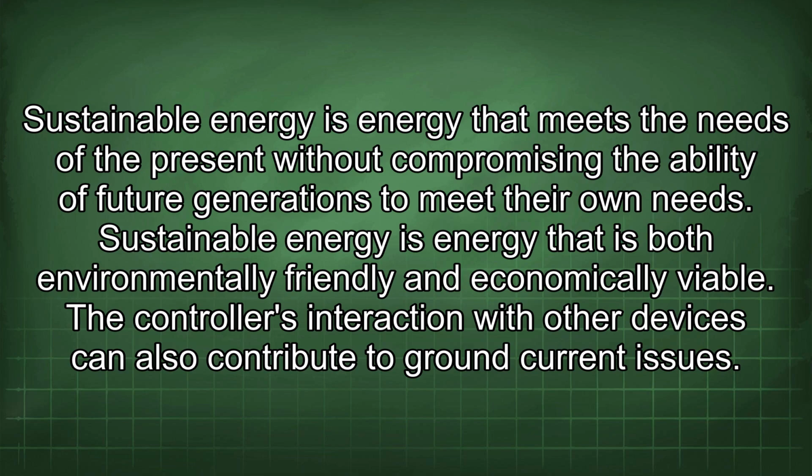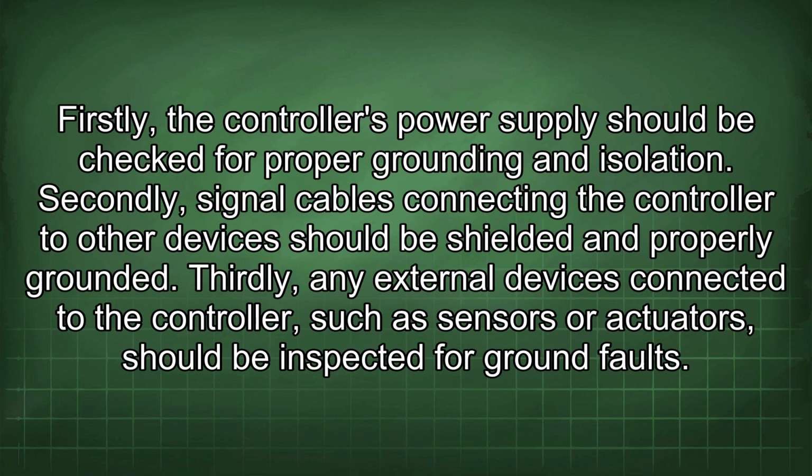The controller's interaction with other devices can also contribute to ground current issues. Firstly, the controller's power supply should be checked for proper grounding and isolation. Secondly, signal cables connecting the controller to other devices should be shielded and properly grounded.